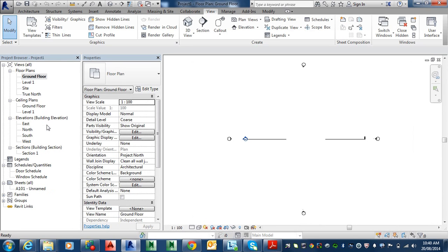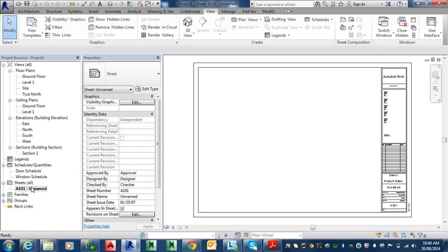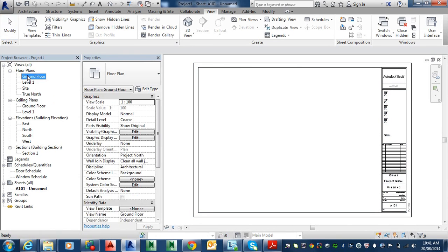If you're used to AutoCAD, there's model space and paper space. Well, there's no such thing as model space and paper space as such, but you can think of this as your AutoCAD viewport and model all in one. All these things here are like your AutoCAD viewport and model. And what you see here is what's going to print out on your sheet. Your paper space is basically your sheet area here. So that's your paper space here, and you put these viewports, you might say, which are actually the model, straight on here, and basically that's how you get a drawing out. But